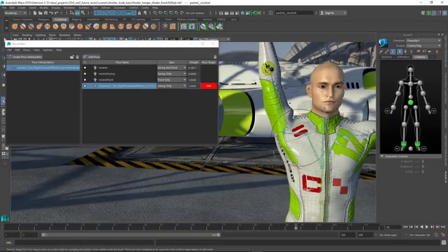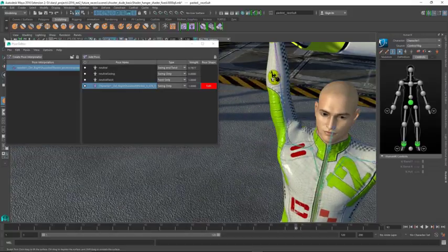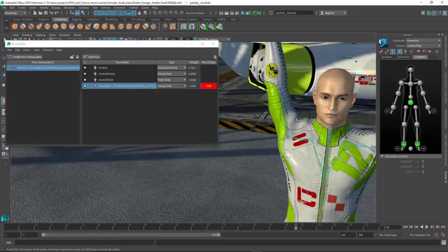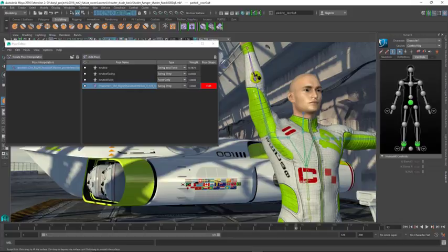At any given time, instead of just a grab brush, I could also go in here and use a simple sculpting brush. If I wanted to really drive that area up a little higher and lift that shoulder, I could do something like that, and then go back in here and smooth that out a little bit. So just by using a combination of painting and smoothing, you can really start to get to an effect that looks a lot better than it did before. I might even want to smooth this region right across there a little bit more.